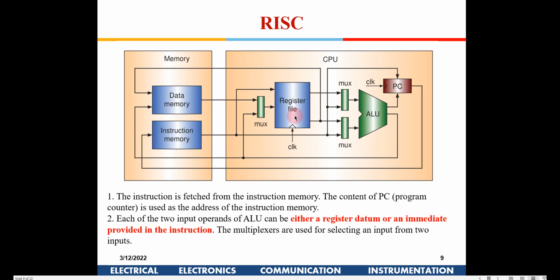When we say we need to load data into some specific memory, we will see that for the load memory instructions, the ALU will compute the memory location. This signal will go and activate that particular address, whereas the data will get transferred from the register only. There is no way data gets transferred from the ALU to the memory. It is always from the register to the memory.